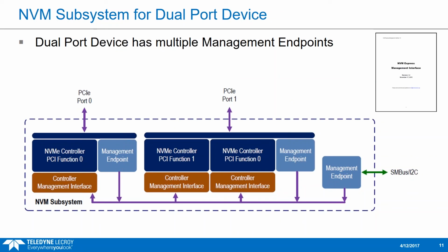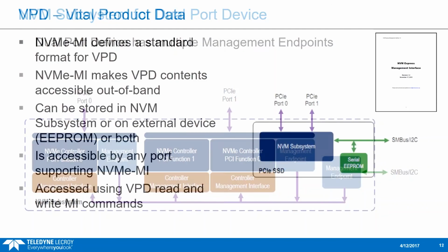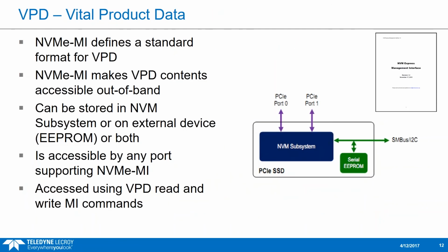Actually, this is a dual port device. So port 0 is one PCI NVM subsystem, and port 1 is two PCI functions, but with also its own management endpoint. So this is again an example from the NVMe MI specification.